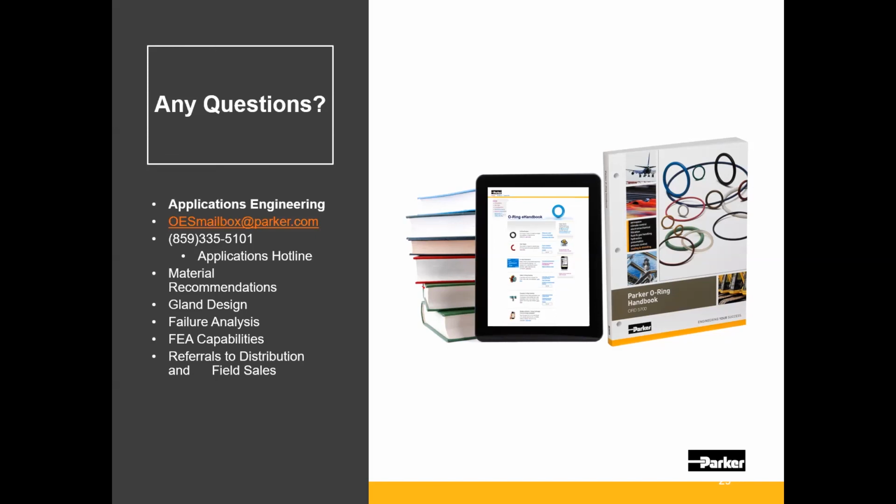A few of those off the top of my head include using the recommended O-ring sizes. There are a number of O-ring sizes that are standard and offered, but not recommended for dynamic reciprocating movement. So staying within the suggested O-ring sizes is a good way, and that has to do with the ratio between the ID of the O-ring and the cross-section of the O-ring.